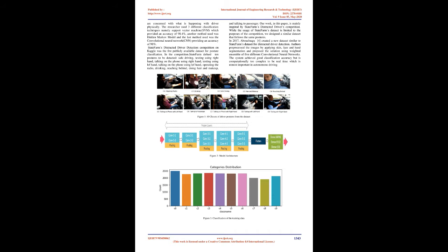Reference 2 provides a solution for drowsiness detection. They took 3 parameters for the drowsiness detection and then subdivided each parameter. The 3 parameters are behavioral approach, vehicular approach, and physiological approach. In the behavioral approach, they try to detect the fatigue of the driver using various parameters such as eye closure ratio, eye blinking, head position, facial expressions, and yawning.